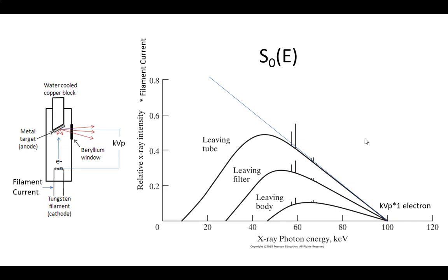So that's the two things. We control this to set what you want to image. The stronger it is, the better penetration it's going to have. So that's going to set essentially how deep of an object I can go through. If you set it really deep for a really small object, there'll be no effective image that comes out of it. You want that depth to be enough to go through, but to have lost a lot, because that'll be the contrast range you can pull out. So too big on this one, it's going to expect a really thick source. If whatever you're trying to image isn't, no good. Okay?